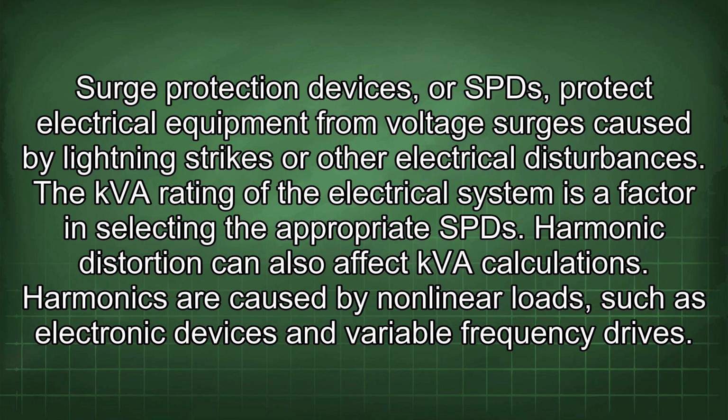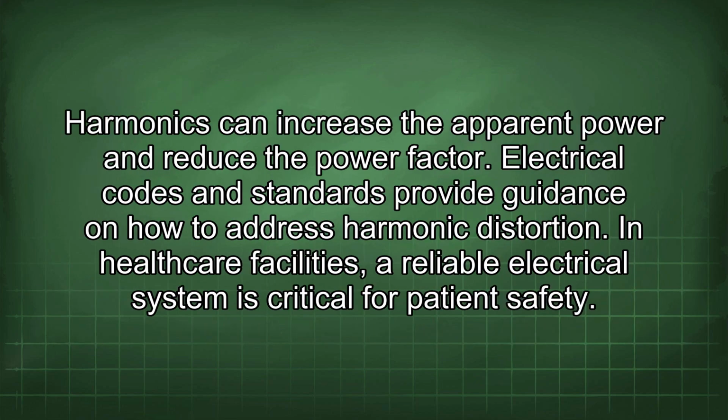Harmonic distortion can also affect kVA calculations. Harmonics are caused by nonlinear loads, such as electronic devices and variable frequency drives. Harmonics can increase the apparent power and reduce the power factor. Electrical codes and standards provide guidance on how to address harmonic distortion.